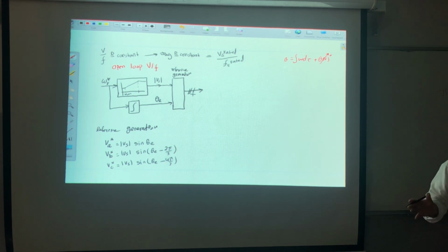So the mechanism in between is the inverter. But the inverter, unfortunately, is a discrete component, correct? Switches, discrete. It can't understand an analog signal. It only understands digital: close, open, 0 or 1. So what I need is to translate those into gate pulses. Good. So if I have the reference and I compare it to a carrier or triangular, then I will generate the gate pulse.